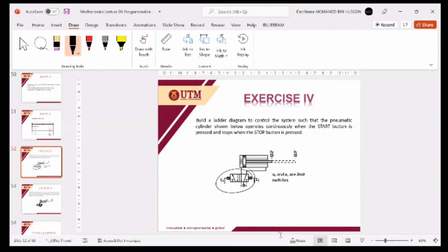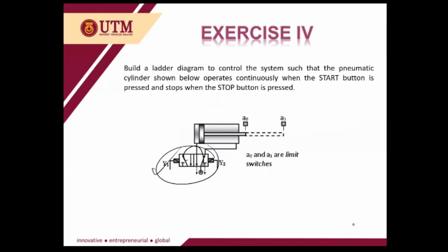If you energize Y1, this part of the valve will be activated and it will keep at that position until you press Y2.